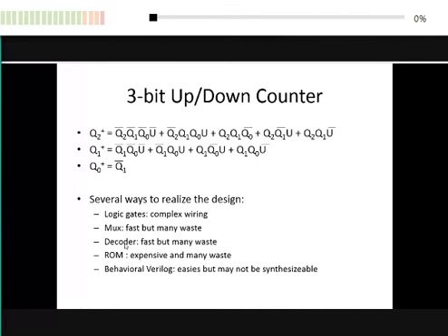Not only just for development, these two MSI devices, the multiplexer and decoder, are my favorite when I use schematic entry. Because after I have done the circuit, I compile and then I simulate. If I find any error, I can quickly make modification. It means that I double check the state table. If there is no error with the state table, I double check from state table to the multiplexer implementation. Is there any 1 or 2 small errors?